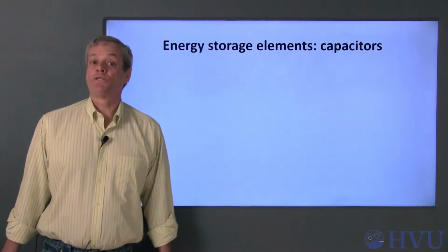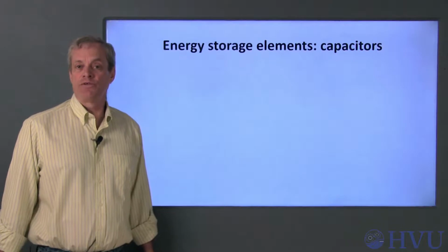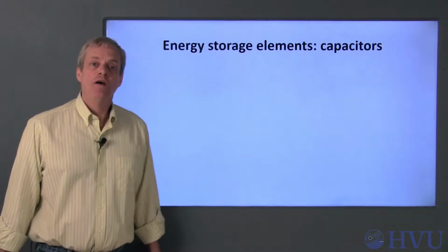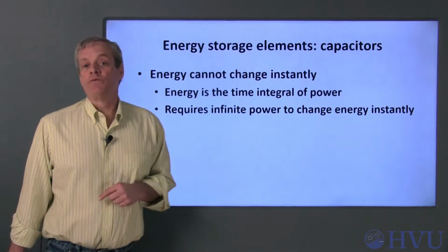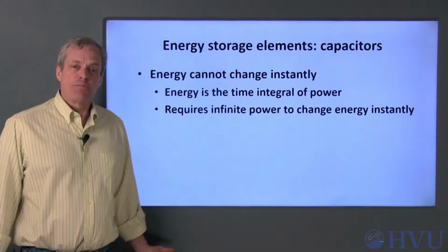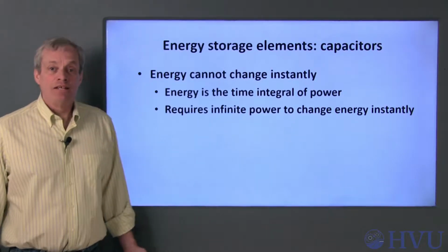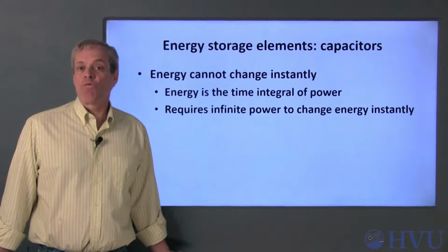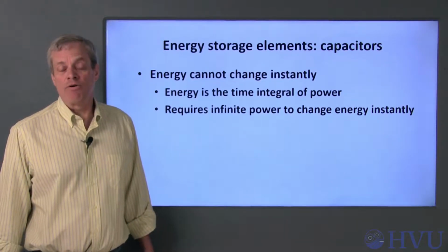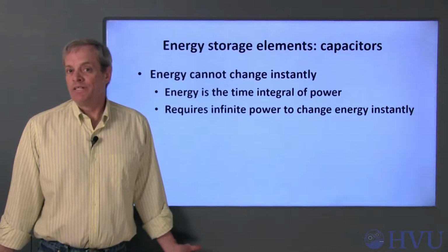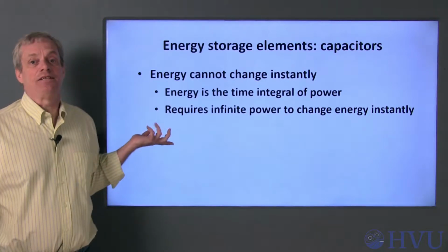In this video, we'll start talking about energy storage, and I'll introduce our first electrical energy storage elements, capacitors. First, I'll go over some basic properties of energy. Energy is always the result of an integration. In more specific terms, energy is the time integral of power. Since energy is the result of integrating power, we can't change energy instantaneously without applying infinite power. Since infinite power isn't realistically available, that means that energy can never change instantaneously.